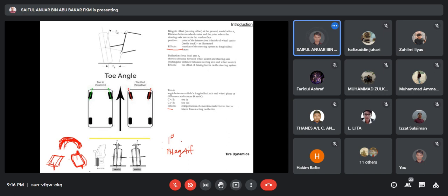Okay, if it's a McPherson strut, we have this. This is our McPherson strut. It looks like this, so the suspension tower, and then it will be slotted into the knuckle arm. This is the knuckle. This is where our wheel is slotted over here. This one is the front view, and in terms of this direction, the side view, usually the slot is over here. So the mechanic still has room to adjust the camber based on the gap of tolerance over here.